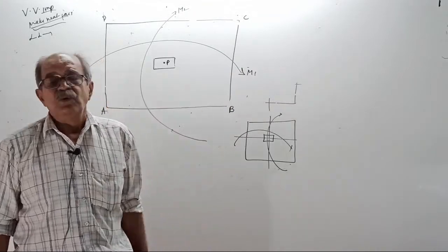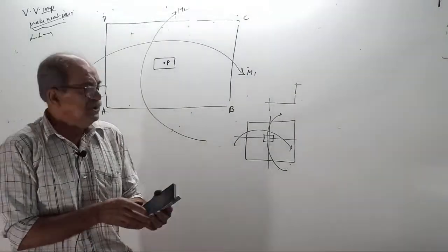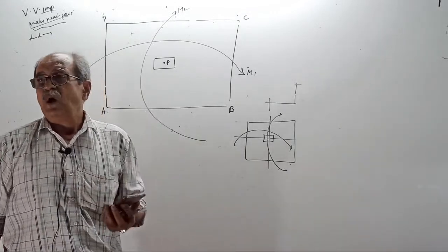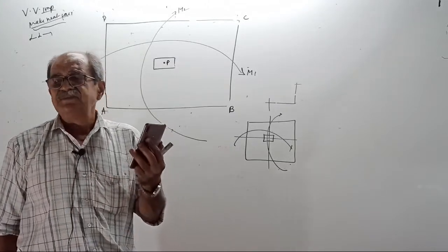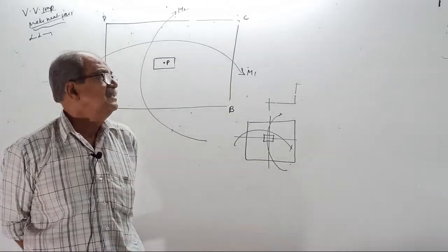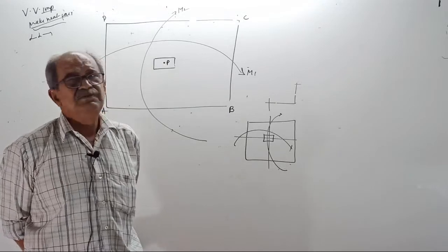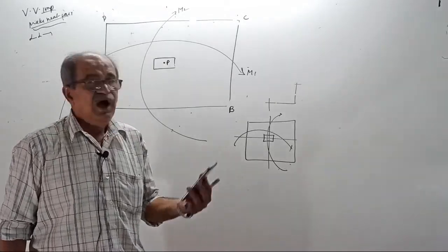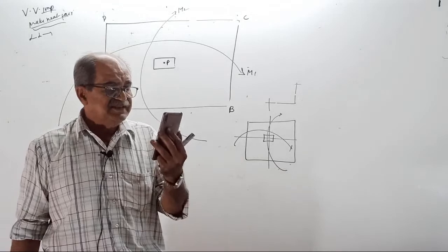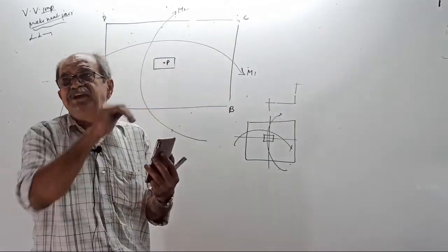So when you consider M1, M2, is P eccentric or axial? Once you consider M1, M2, your P becomes axial or eccentric? Not answering. Once you consider M1, M2, P becomes axial. Clear? Who told eccentric? How? The eccentric load is shifted to the CG of the column.